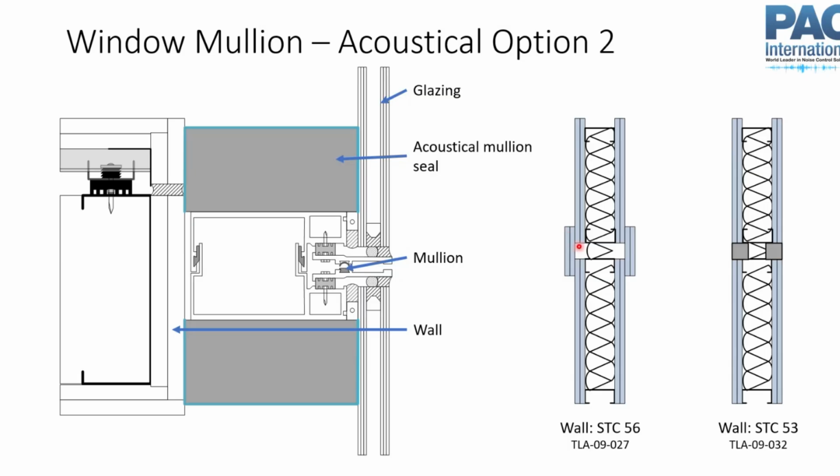So testing this, you have the wall with the gap sort of built into it, but with drywall cover pieces. This is your base case. And then you take the cover pieces off, you put your seals in, and you test that again. And you see there is still some reduction in this, but you mostly maintain your acoustical performance. And if you just had this gap in here without these seals, this would be an STC 30 wall or something like that.